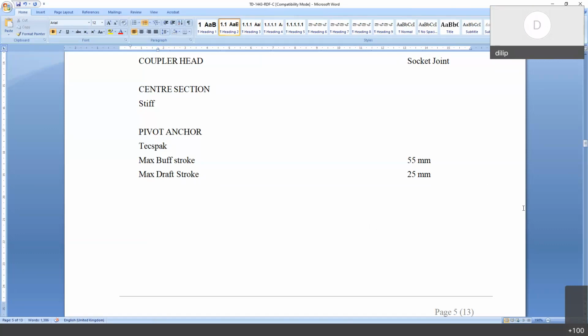These window glasses are basically double glazing units, like our regular LHB also. So, in case of any damage of the window, generally the top glass only will get broken because there is a gap between the outer glass and inner glass. There were problems even the first train when it was running, lot of windows were broken by miscreants. Thereafter, we have provided a protective layer over these glasses. And we never experienced the case where something was thrown and complete window got damaged; that type of case has not come across.